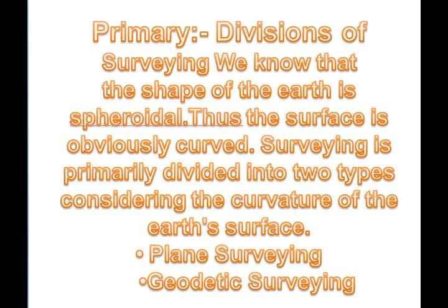There are primarily two types of surveying which we take into consideration. One is plane surveying and the other one is geodetic survey. In plane surveying, we assume that the surface of the earth is absolutely flat, and in geodetic survey it has a curve. The difference between both of these is defined in the heading over here.